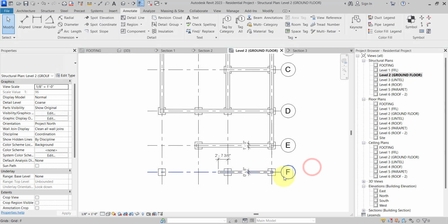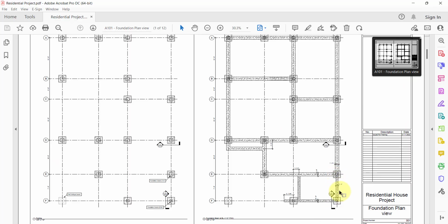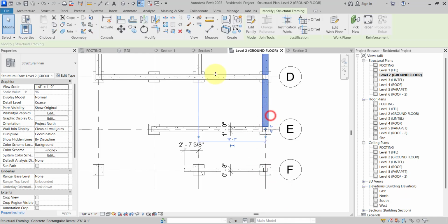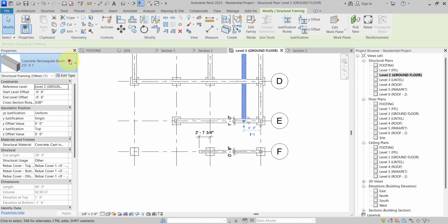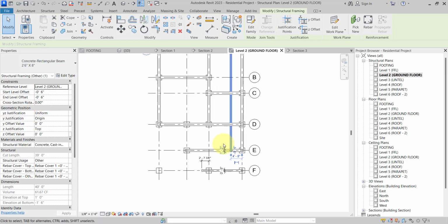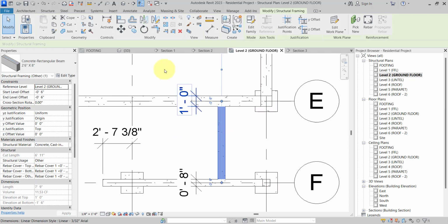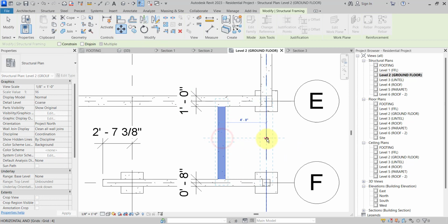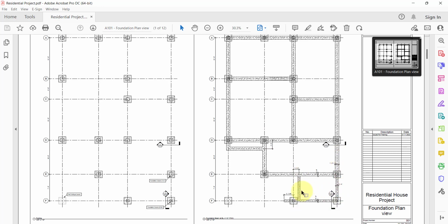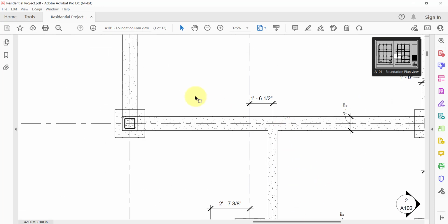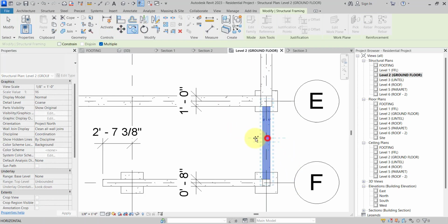Okay. Now here we also have another beam, right? So that beam is 8 inches. So we can copy this beam. I am showing you a different manner than just drawing. Copy paste. So just stretch to the downward direction and move the beam from center to the grid intersection. And now as you can see, this is my 8 inches beam, right? This is also my 8 inches, but this beam is located at certain distance. So let me approximately copy it from here to here.